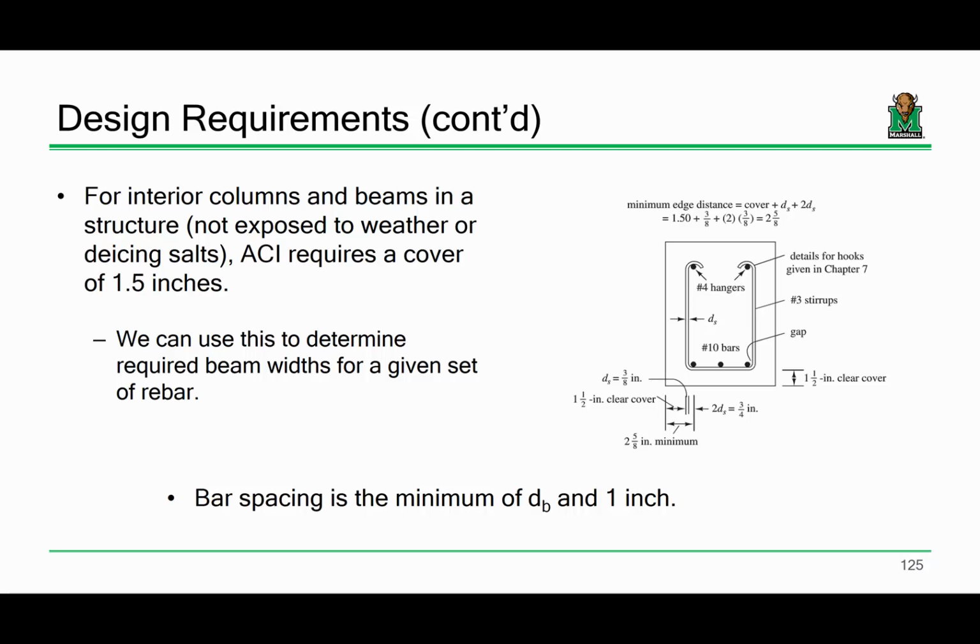But does that make sense? Okay, all right. So typically, for concrete that we use, let's say in beam applications, we have a limit on our bar spacing. We can bundle bars, like we can actually wrap bars together in some instances. I actually don't recommend it, but you can if you need to.